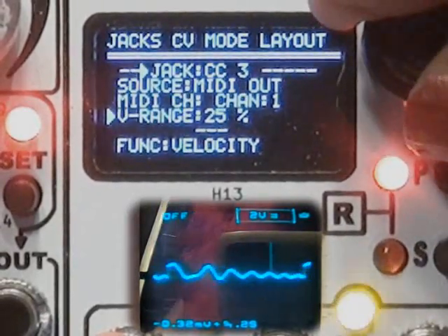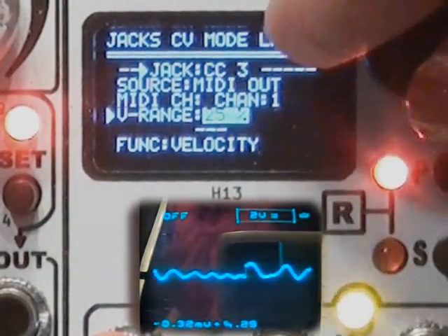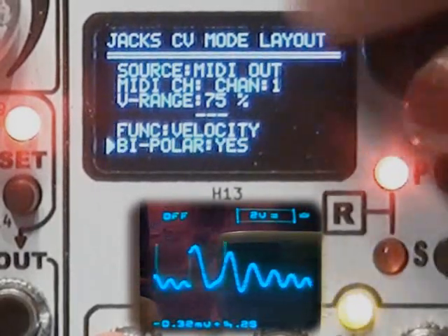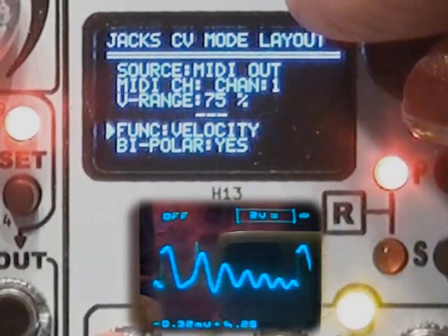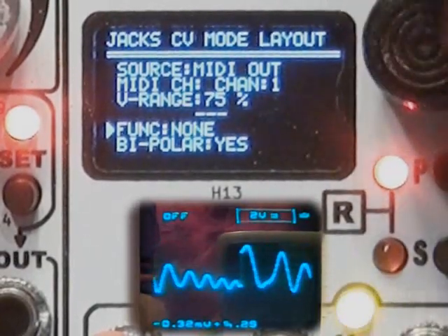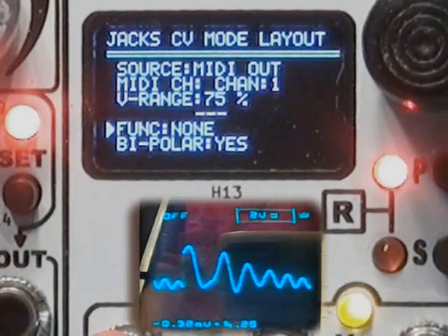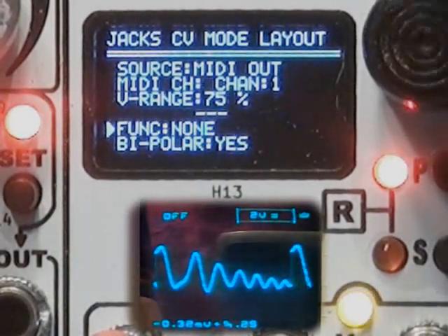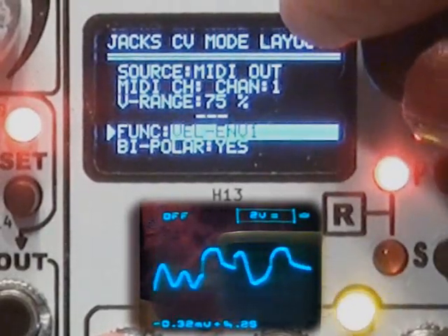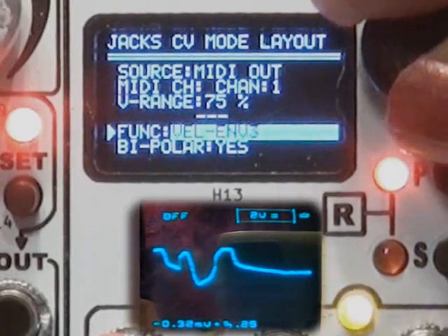You may have noticed thin spikes on the oscilloscope display. This is from gate CV row's velocity also getting sent to this jack. To prove that, I'll turn off the velocity. Any other function can also be dialed into this jack, even though the direct envelope 3 is targeted here. One will override the other depending on if the previous one is finished. This can make very complex envelopes.